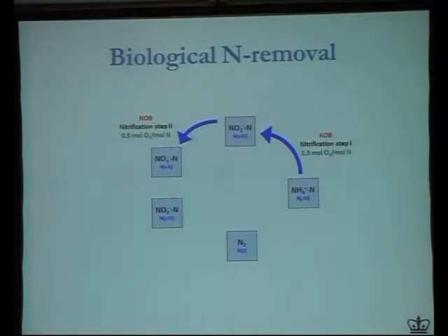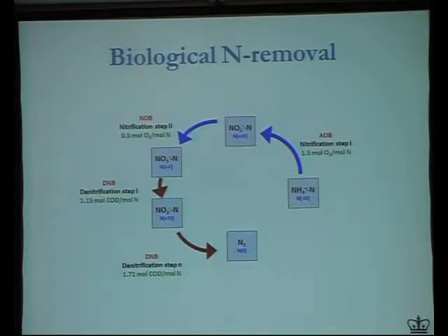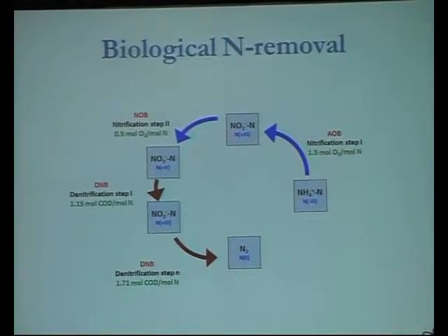Conversion to nitrate is not removal because nitrate is still fairly soluble, even more so than ammonia, and it is also somewhat toxic. Removal of nitrogen is by virtue of converting the nitrate to dinitrogen gas. And nitrogen gas is fairly insoluble in water and gets stripped out. That is removal. But in doing so, in engineering the nitrogen cycle, we have put in a lot of energy and we have put in a lot of money, and we are producing nitrogen gas.